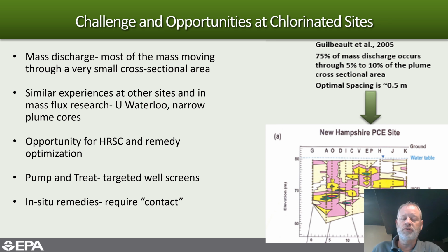For instance, pump and treat has been shown to work quite well in places where we know a lot of the mass is moving in transmissive zones, and if we can target those transmissive zones with the right screen intervals, pump and treat can be effective, and has been shown to be effective at some sites.